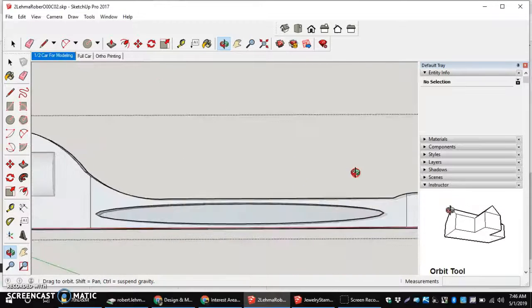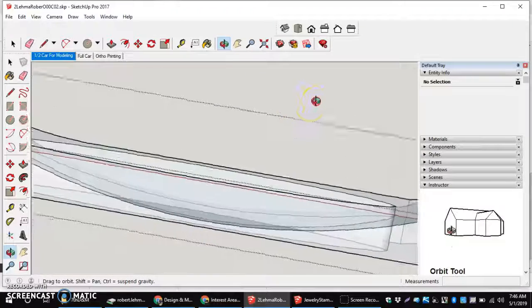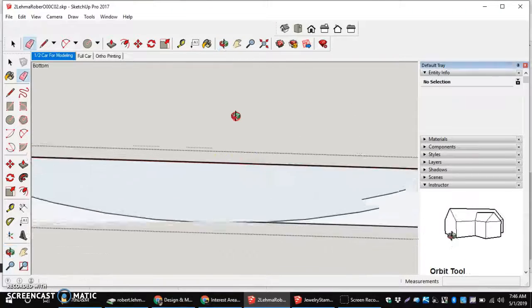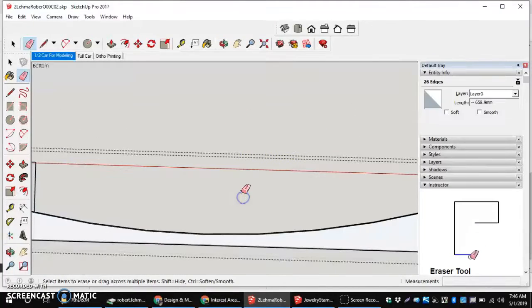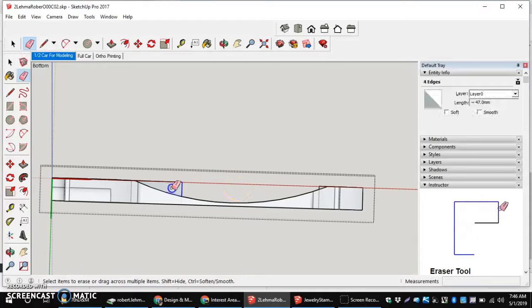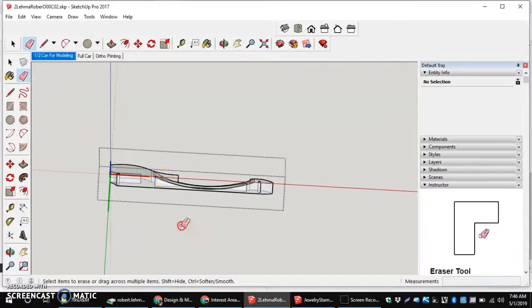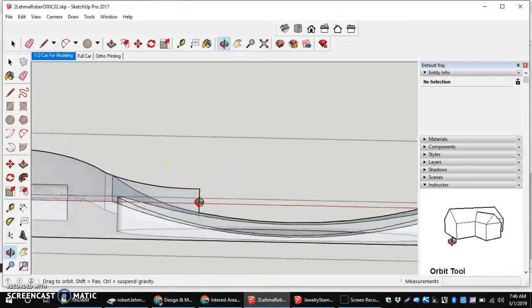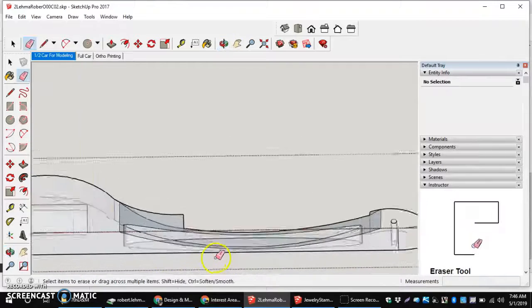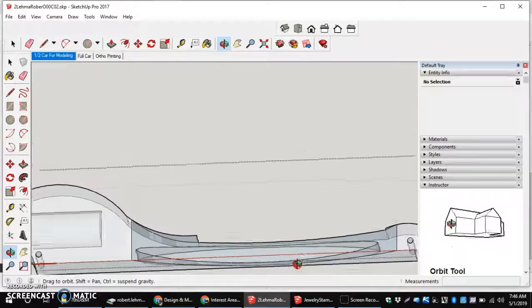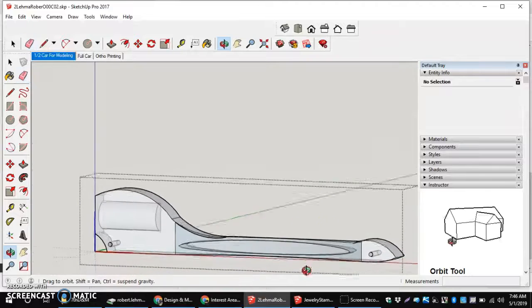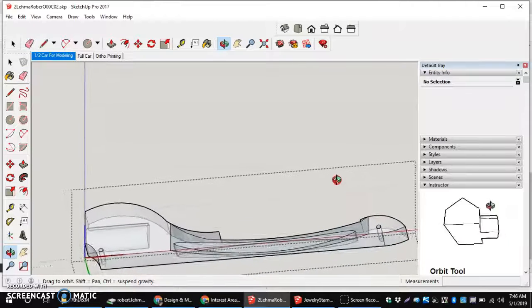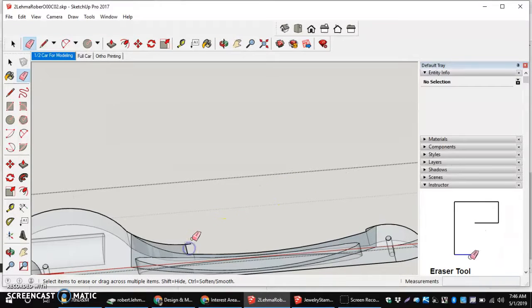And then I'm going to go to the bottom view, look straight up at it, and I'm also going to click and drag through here. And then right here. Oh, edit, undo. I deleted too much. I noticed that by looking at it. And one thing to do is always pay attention to your last deletes, because if you end up messing up or deleting a surface you didn't want to delete, you can always go back and edit, undo it.